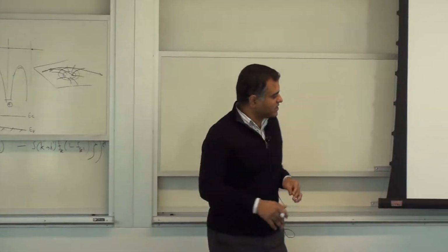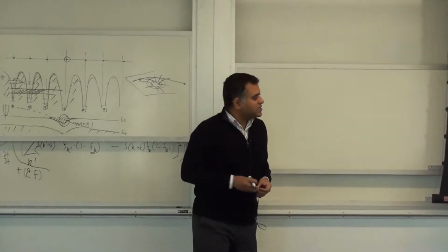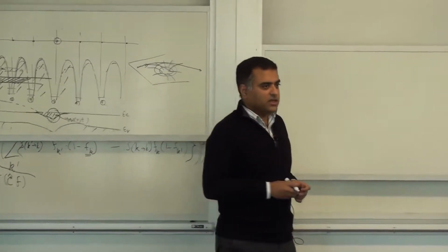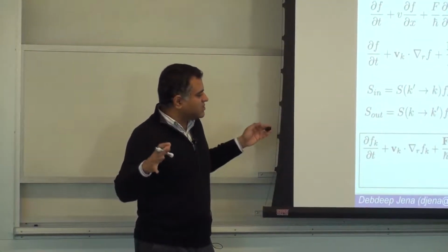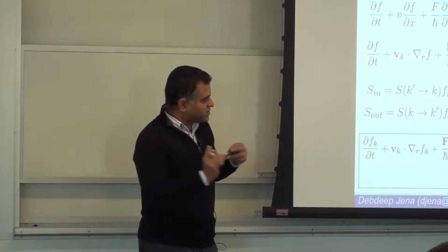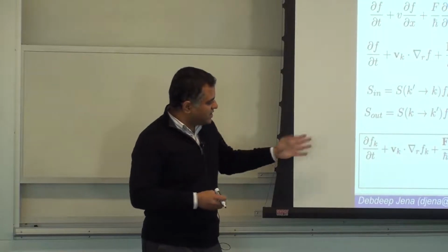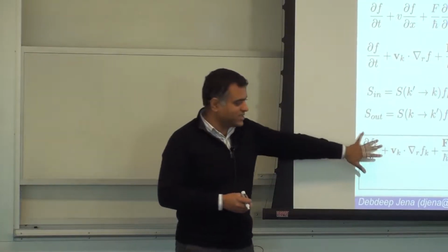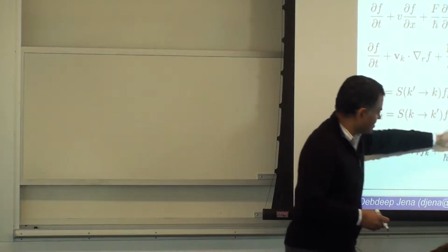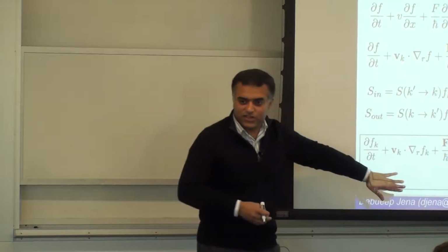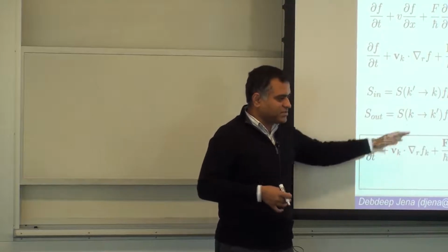So you can have a hierarchy of these Boltzmann equations, and this is actually used in semiconductor design software today. You can set up the Boltzmann equation and a k-space grid and let all kinds of scattering, based on the doping you have and other things and temperature, be solved numerically, and you find out the result. And if you are emitting into phonons, you can couple it to the phonon system, because the electron and phonon systems will be coupled now, and you can solve them together and see how much heating of the crystal happens by just tracking this throughout.